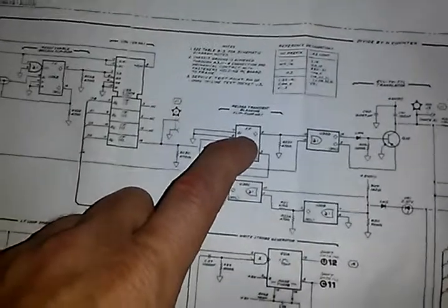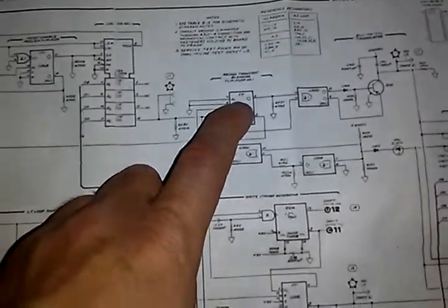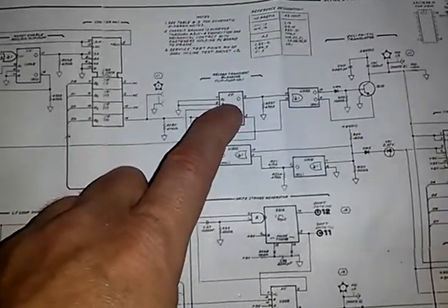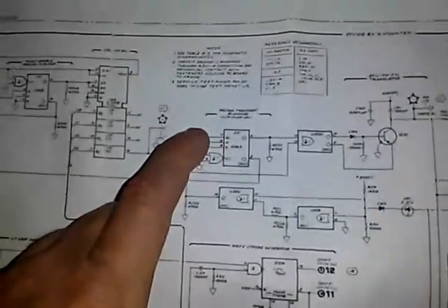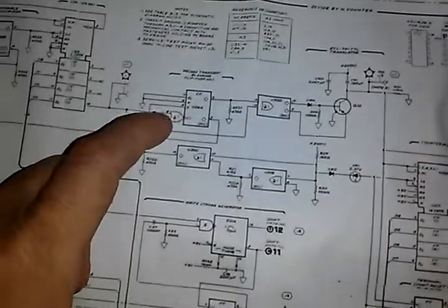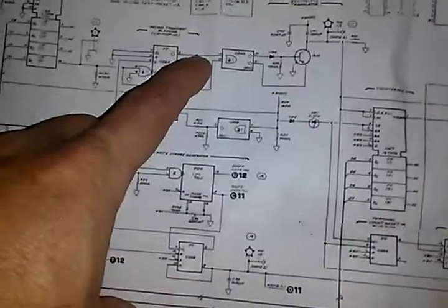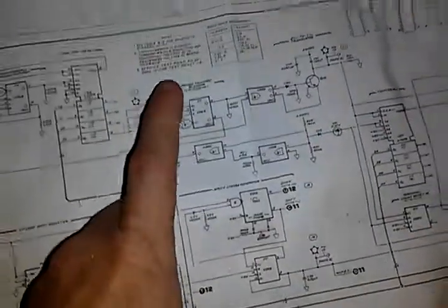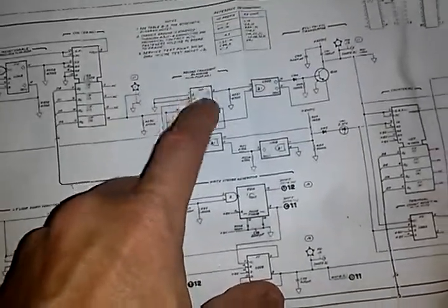The chip was getting power. I checked that it was grounded, and it was getting, I think, 5 volts on it. I forget. I guess ECL would be 5 volts, and positive ECL would be 5 volts. Yes. And I checked that it was getting all clock signals to it, which it was. No activity on this whatsoever. The point is, I bought a new chip, put it in, and this right here was bad.